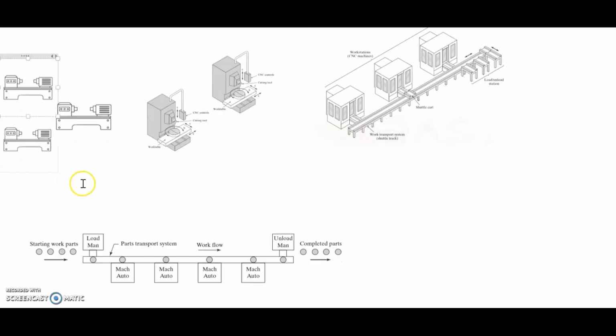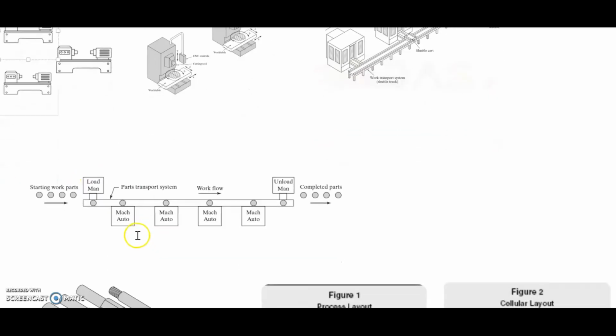If there are multi stations, but the sequence of operation is variable, we call it multi-station with variable routing. So the part or products in this multi-station are processed in a variety of different sequences. This is what is implemented in cellular manufacturing and flexible manufacturing system, or FMS.